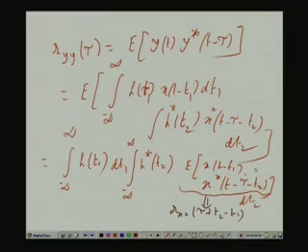So the autocorrelation function, as we wrote in the beginning as a function of tau, is indeed a function of the lag only. This proves that the output is WSS if the input is WSS and the input signal is passed through an LTI system. The moment we say the output is a WSS signal, immediately the question comes as to what the power spectral density of the output is.